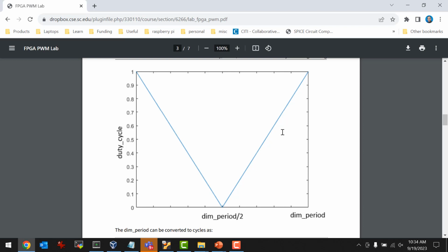Now you might say, wait a second, how does the software know the speed of the PWM, or how does it calibrate? It's the cycle counter, that performance counter. The software has the ability to see a 50 megahertz cycle counter, and it's going to base all of this off of that 50 megahertz. So basically you're going to convert a 50 megahertz counter into a PWM signal and into this dimming effect as well, right?